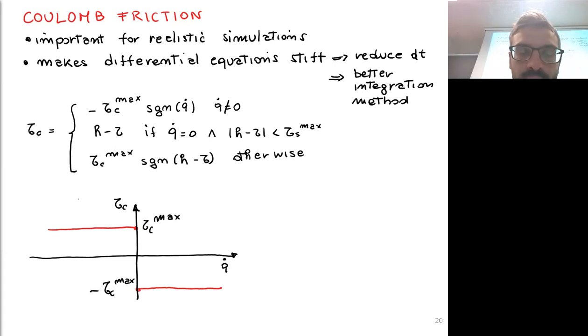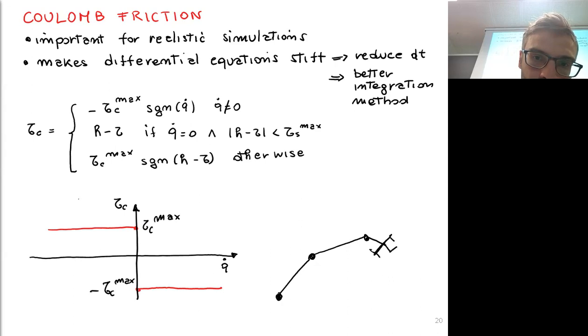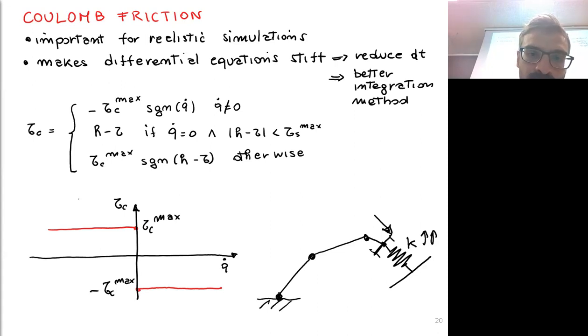Yeah. Another example, which we will see in the next lecture, is whenever you have the robot in contact with a stiff environment that is represented by a spring with a very large K. If you think about pressing against the spring with a motion, the manipulator itself will have some dynamics, so it cannot move faster than some rate, let's say some natural frequency, and the actuator capabilities and everything are such that the motion cannot be larger than something. But if you have a very stiff